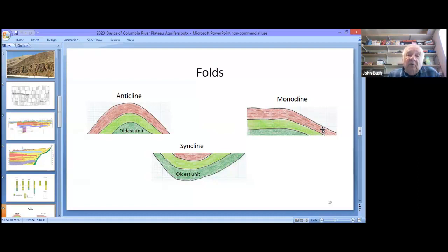Research since the 1950s has shown that when groundwater comes across a fold, it can do a couple of things. Obviously, you've bent the interflow zones, so some of these structural features have been shown to be impediments. In other words, if you go into the center of an anticline here, because fractures have been compressed, that fold can become a barrier to lateral movement.